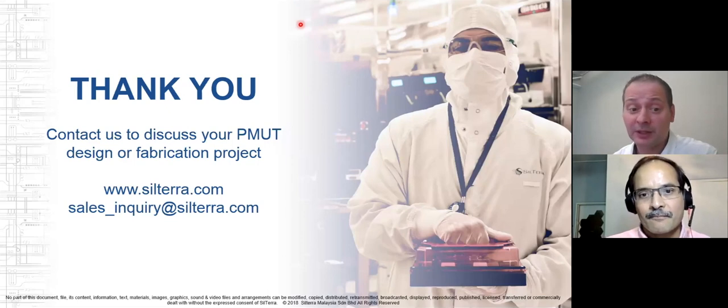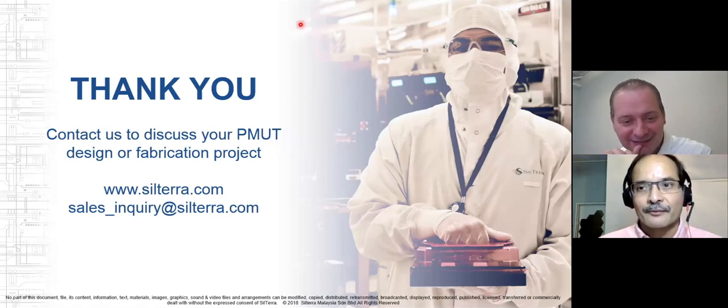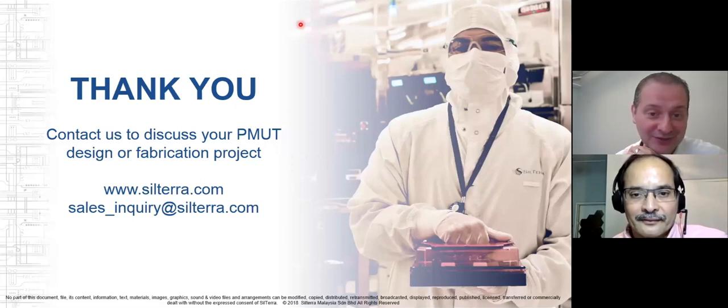What's the minimum piezo thickness you can deposit? Well, that's a good question. We never really tested what the minimum is, but for sure we have gone down to 4,000 angstroms, 5,000 angstroms. But I'm sure the tool is capable of depositing even thinner films if there is a need for such an application. These are very specific questions.